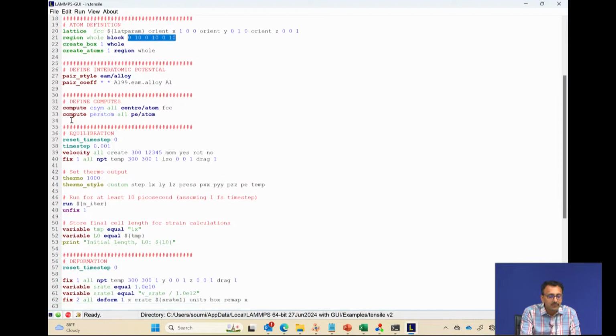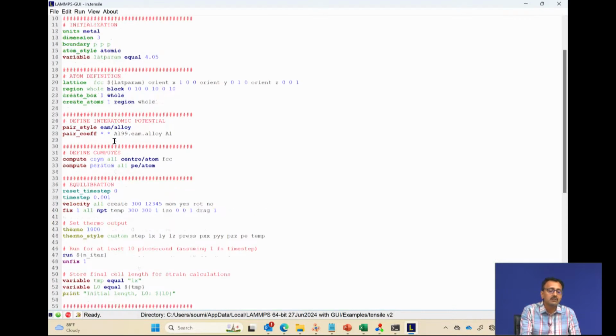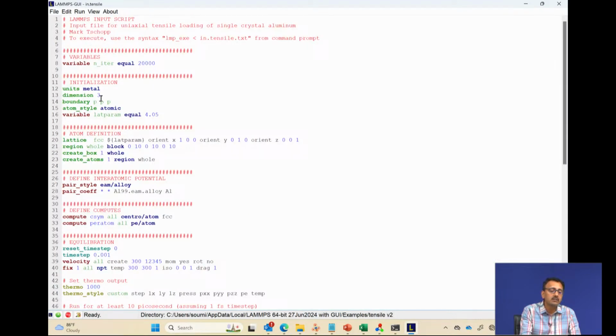So, the first step in the actual calculation is an equilibration run. In MD simulation, when you are trying to equilibrate, you have to set up the conditions. You are starting with time 0 and you need a time step now. In the previous calculation, energy minimization, there was no time step because it was a static calculation. Here you have a time step of 0.001. So, what is 0.001? That is where the units come into play, and they are very important.